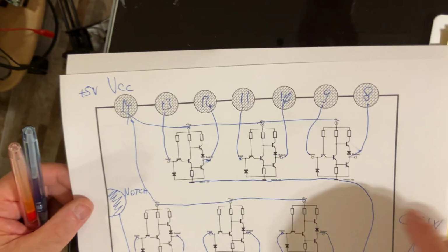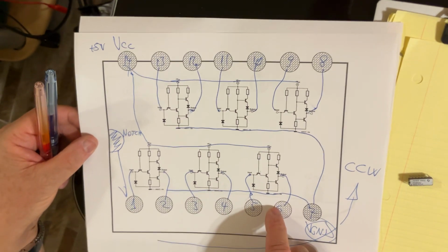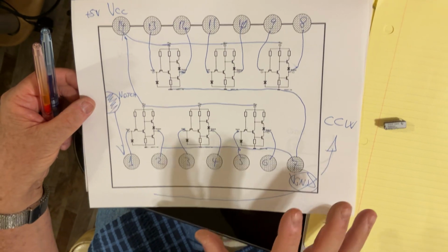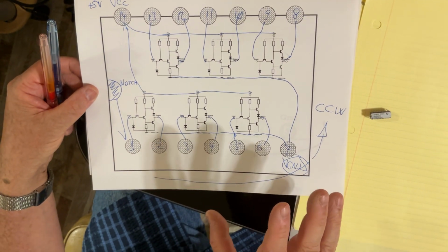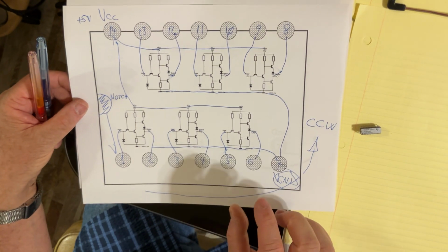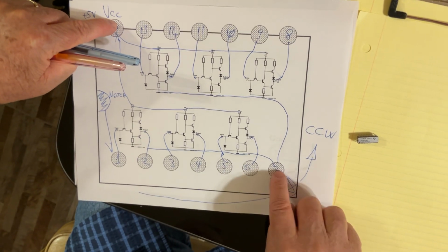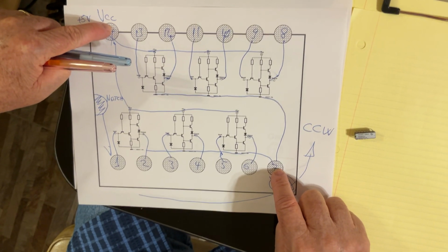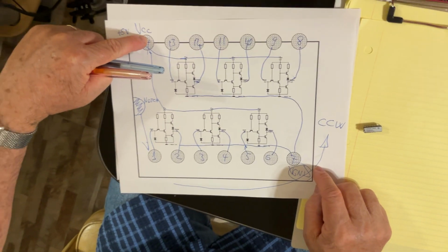Inside this little box, there are 6 identical diagrams, each of them representing one inverter. Why 6? Since these packages were first designed, the logic circuits, the TTL, were designed in packages with at least 14 terminals. If you remove the 2 terminals for the power, one for the power supply and the other for the ground, out of 14, you remain with 12. And because one inverter only requires 2 wires, one input, one output, 12 divided by 2, 6 inverters